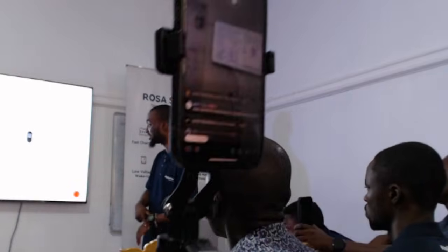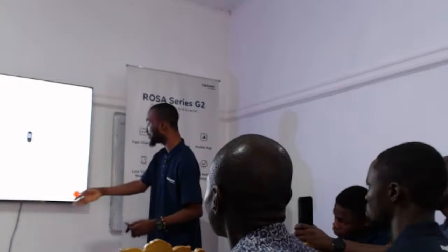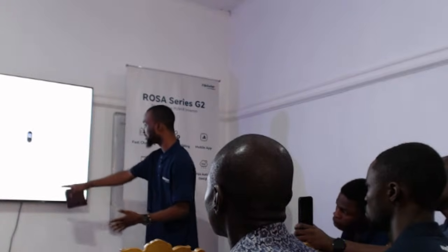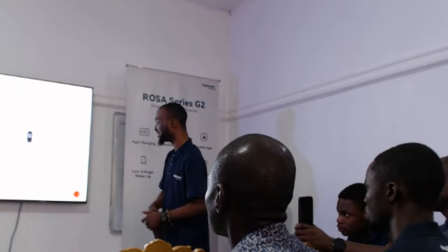This is for 11 kilowatts. This inverter has 2 series. Pulse S2 has both 8 kilowatt and 11 kilowatt, but our case study here is 11 kilowatt. We have 11 kilowatt here in Nigeria, but next year our 8 kilowatt will arrive in Nigeria as well. So the grid breaker is 250 VAC and 80 amps, and then the backup breaker for the load too is also 250 VAC and 80 amps.